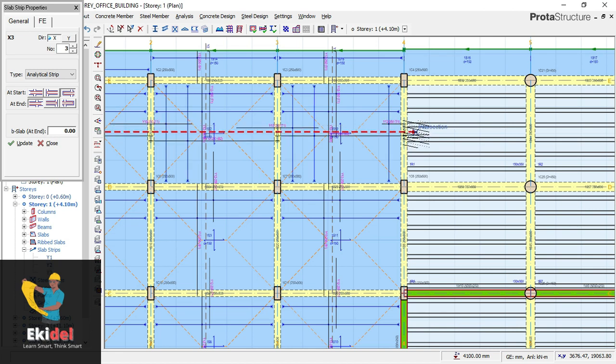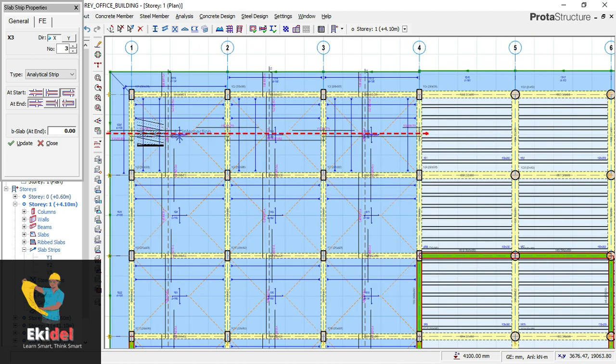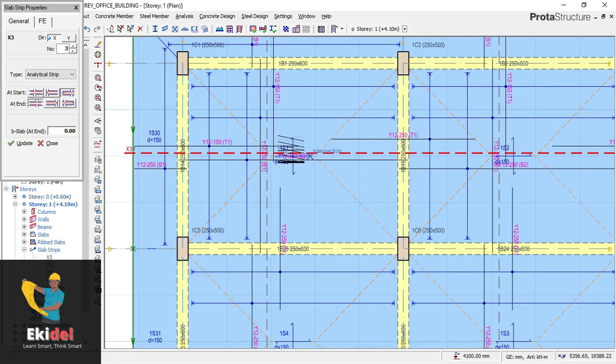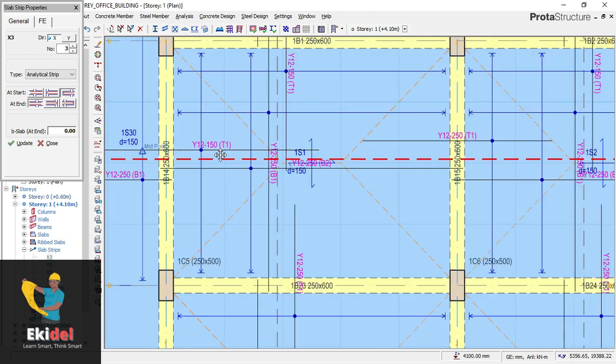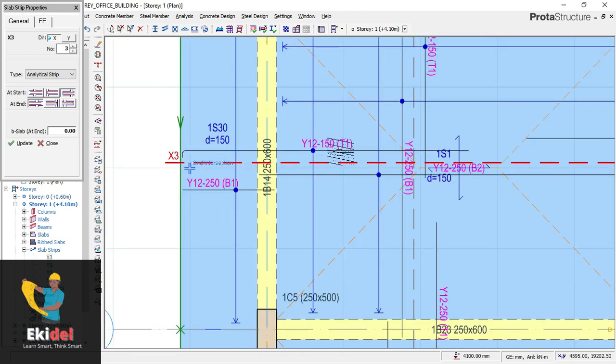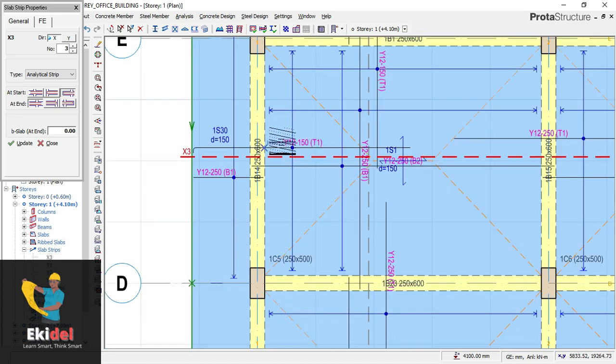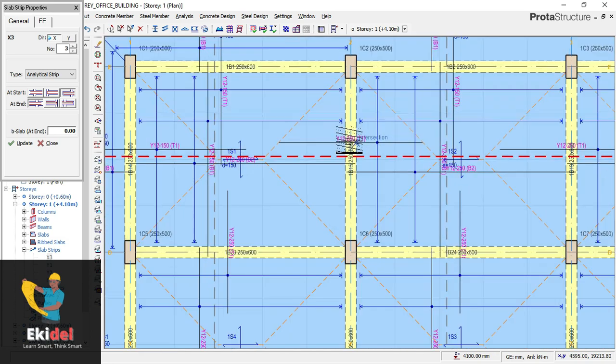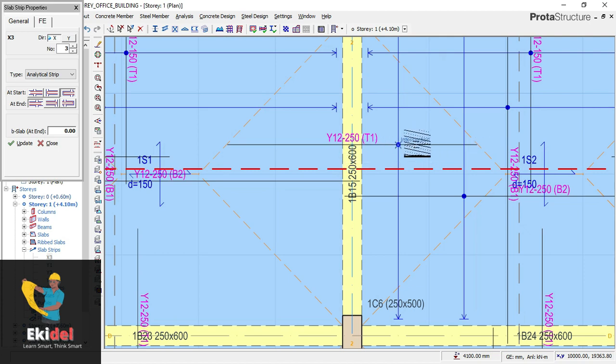Automatically it will detail for the X direction, as you can see here right now. So we now have our slab detail for the X direction, which gave us some of the spacing for this very end. Because of the cantilever, as you can see here, it gave us that this place should have a spacing of 150, and you can also change your spacing to your preferred value, which I'll show you in my next video, how to change your spacing to either 175 or 200, which you want as your maximum spacing.